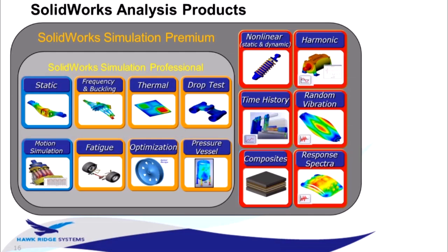The good thing about the SOLIDWORKS analysis interface is that the processes and the techniques are identical, well, very similar, regardless of what analysis type you're doing. So if we learn good practices here in doing static stress analysis, they're going to be equally applicable for any other analysis type on the screen.